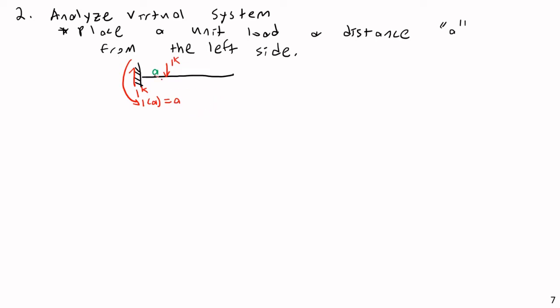Now, why didn't I use X here? That is tempting, but the problem with that is I am going to already have to integrate as a function of X. I'm going to have to integrate our moment functions down the line with an X dx. And so in that integration, we're really trying to integrate the moment, not the actual A. A is a constant. Regardless of where you analyze your dx, the distance of this unit load is not changing. It's still just at position A.